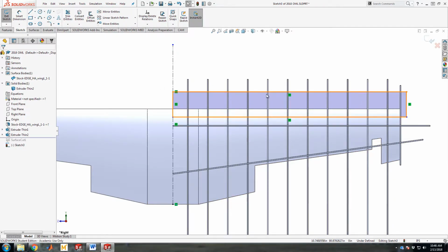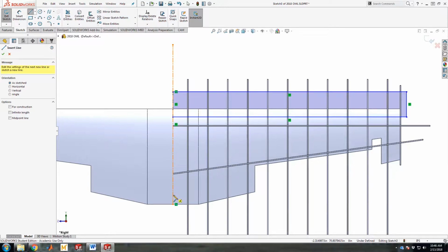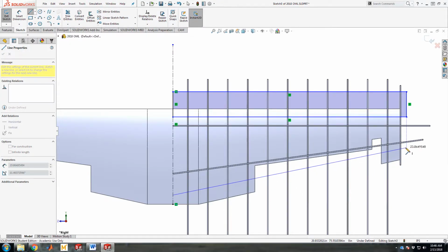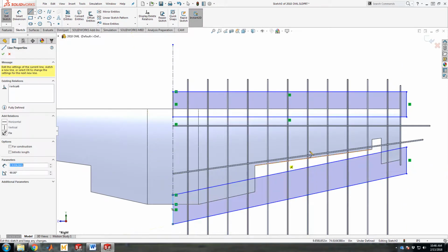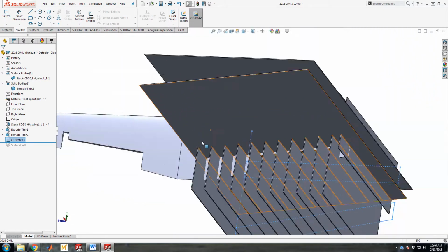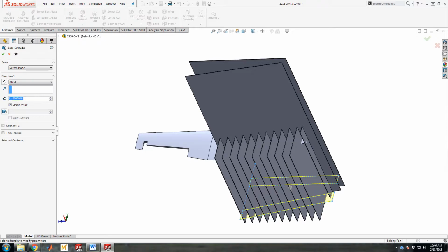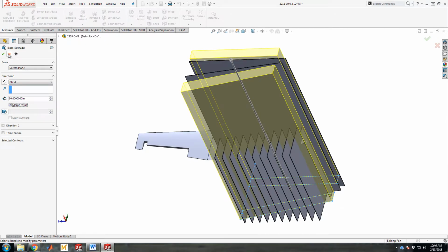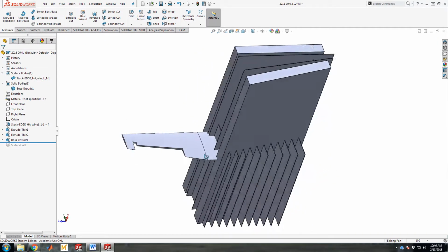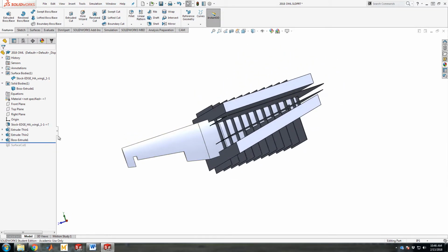So this solid region sketch there is going to become the leading edge stock, and then I'll do this with a different line. The trailing edge stock, meaning the solid portion that makes up the back side of the wing, we will trim out of a solid line that looks like that-ish. Same way, we'll go ahead and extrude this as a solid. The nice thing about this whole process and this method is that you can make this out of super, super simple shapes. I mean, these are blocks. And so, yeah, all right, we'll go with that for now.